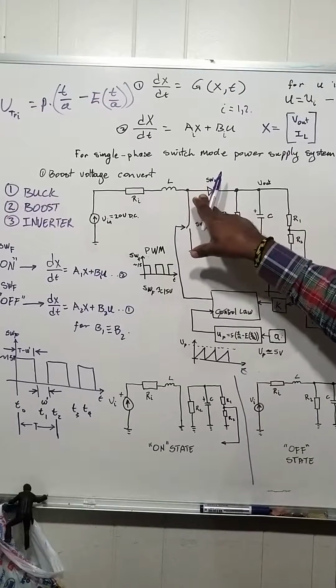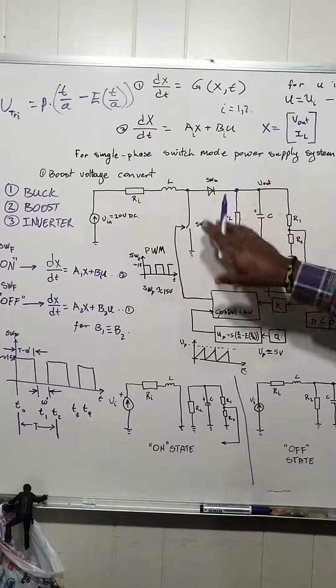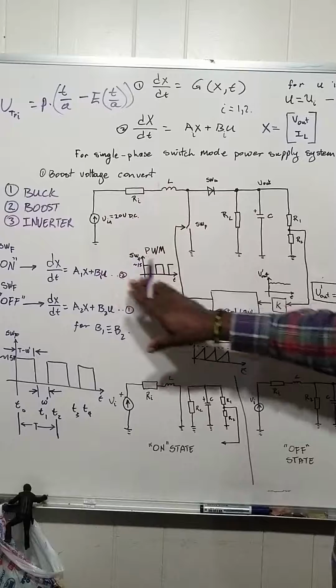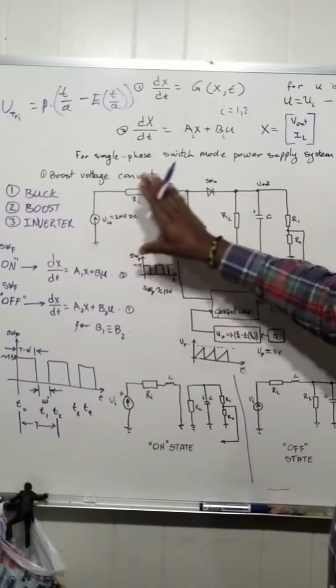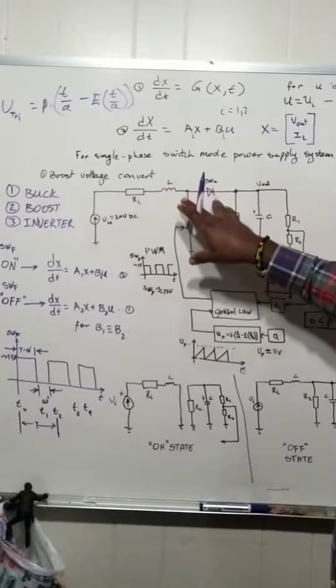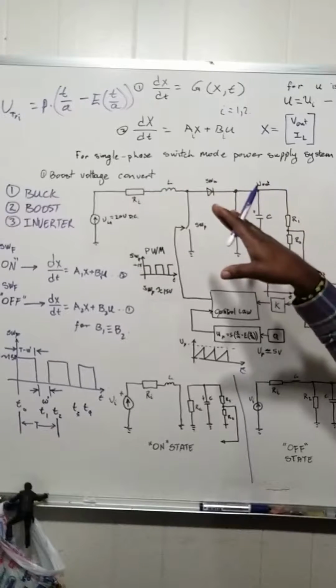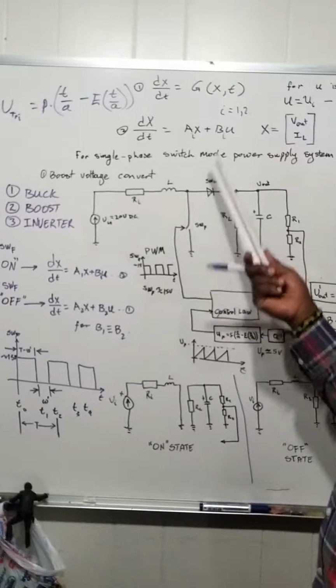That ends up creating a reverse current in the diode. So the diode becomes an open switch, and nothing flows in this direction. So the circuit literally induces energy, and that actually creates an issue with the diode. So it's not in forward bias, it's in the what? The reverse bias. So when this diode is in reverse bias, it's open.